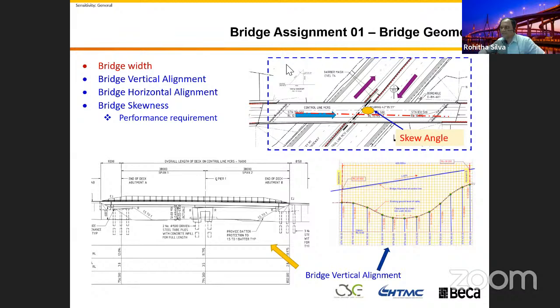The classic example here is the motorway. You want to build an overpass above this motorway, linking this side and the other side. You can see when you place the girders and the bridge piers, you can't put them perpendicular to the bridge control line.